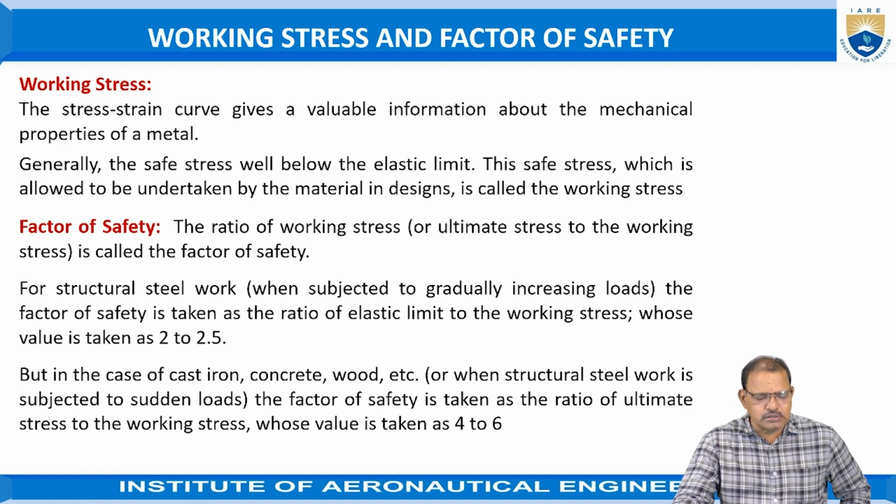The stress which is allowed to be taken by the material in design is called working stress. It is always below the elastic limit. The elastic limit is the point up to which, when the applied load on the metal is removed, it will regain its original shape.